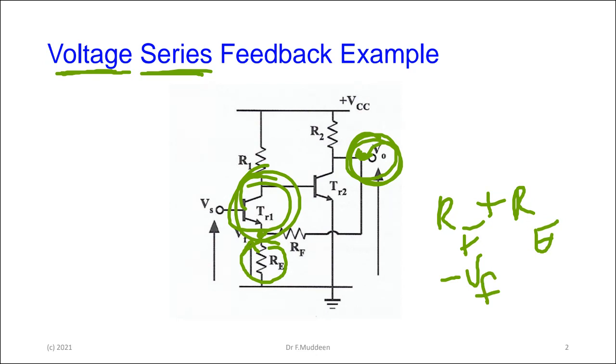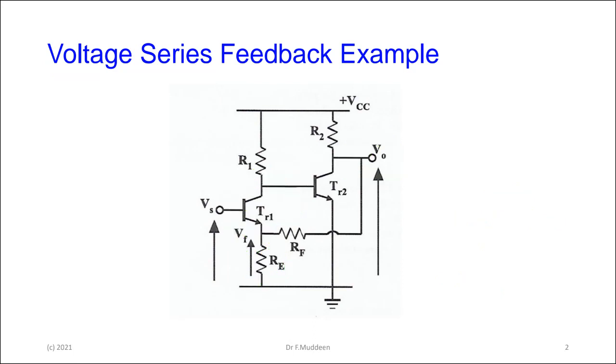This is a simple way, with just one resistor, as we said. You just have to tie it back, and we said the feedback networks are usually just a passive component or two. Everybody's seeing that voltage being sensed and the feedback voltage being developed across the emitter resistor here. Voltage series feedback.